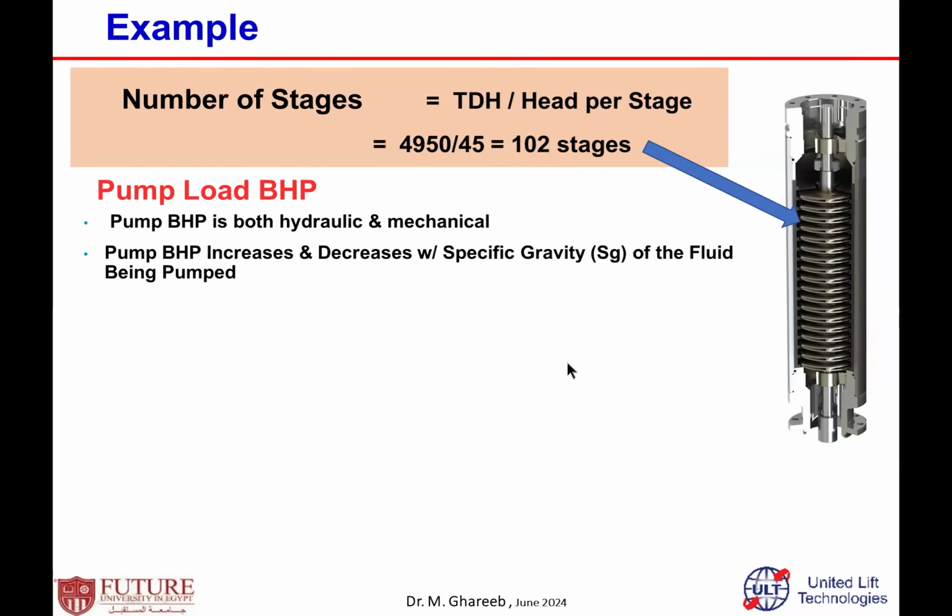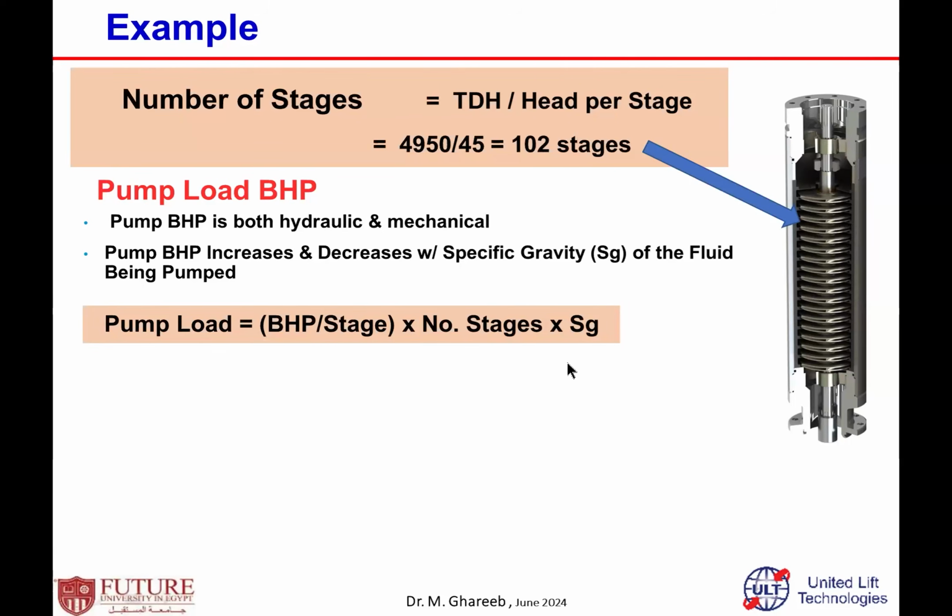of the fluid. Take this into consideration when you're sizing the motors. This well is currently initially producing only oil, and with time, how much water cut do I expect? The water specific gravity and the oil specific gravity, I have to consider when I start sizing the motor or calculating the brake horsepower. Then the pump load is equal to the brake horsepower for each stage multiplied by the number of stages, and depends, as I said, on the specific gravity of the fluid.